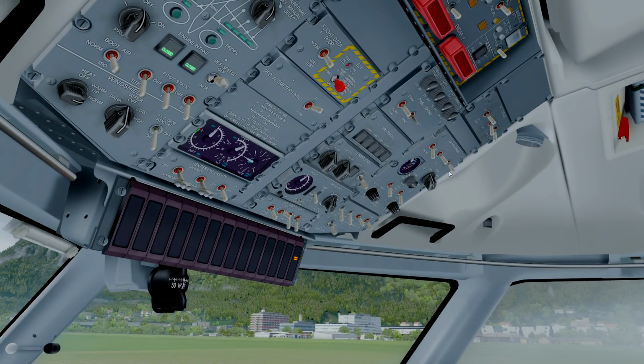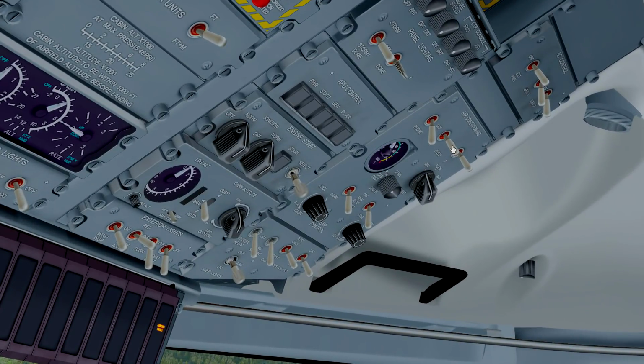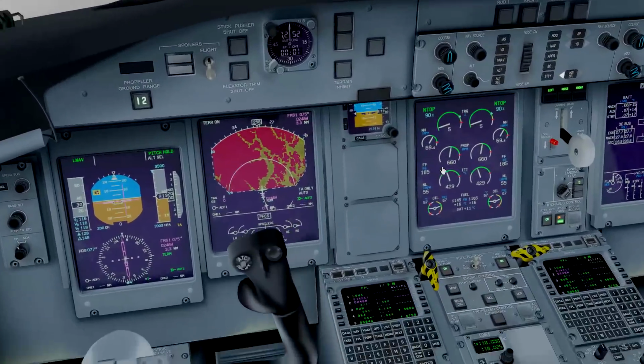Okay, so this just makes sure that all the power is actually going to the engine, so no performance is lost by providing bleed air. Just make sure that if you're performing a bleeds off takeoff, you turn the bleeds back on after departure, of course, because we want to pressurize the cabin properly. So don't forget these switches. In this case I'm going to leave them off for takeoff because, again, this runway is relatively short, so we don't want to run into trouble.